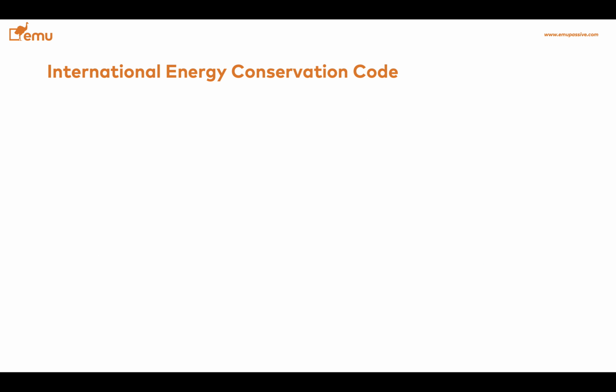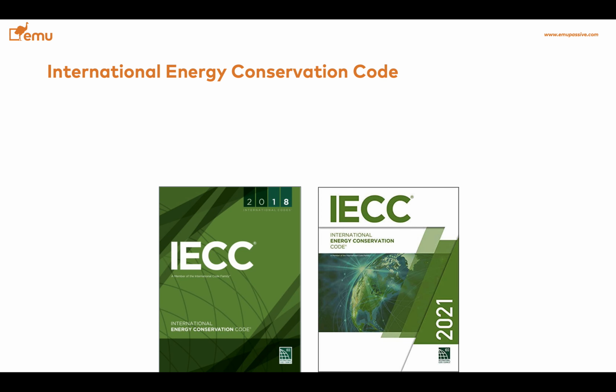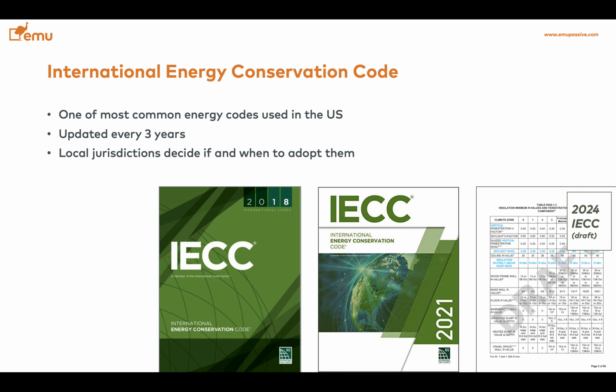Now, we are starting with the International Energy Conservation Code, IECC. These are the covers. We looked at the 2018 as well as the 2021. And we also used an official draft of the 2024 IECC to see how that could shed a light on the direction that the building code is going. It's one of the most common energy codes used in the US. It's updated every 3 years. Local jurisdictions decide if and when to adopt them. For a lot of jurisdictions in Colorado, 2021 is the future, although this is being recorded in 2023. And home rule allows significant changes being made once the code is adopted.